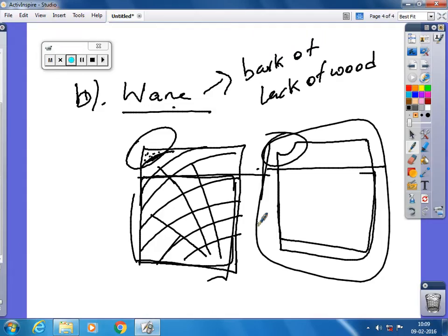If you properly square the edge, then we can increase the strength. You clear with knot and vein? What do you mean by knot? How are knots formed? Absence of sunlight, and when there is a cut in the tree, when a branch falls or a limb falls, we find a knot over there.